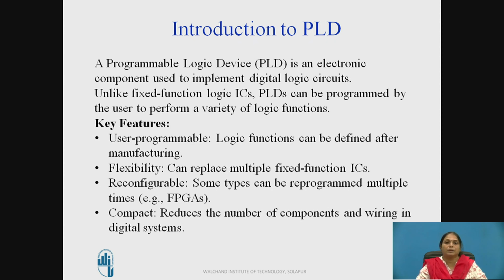PLDs, programmable logic devices, are electronic components used to implement digital logic circuits. Unlike fixed function logic ICs, PLDs can be programmed by the user to perform a variety of logic functions. The key features are: they are programmable, so logic functions can be defined after manufacturing; they are more flexible, as they can replace multiple fixed function ICs; they are reconfigurable, as some types like FPGAs can be reprogrammed multiple times; and they are compact, with a reduced number of components and wiring in digital systems.